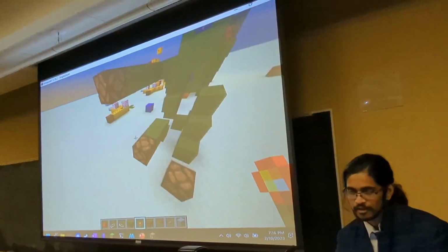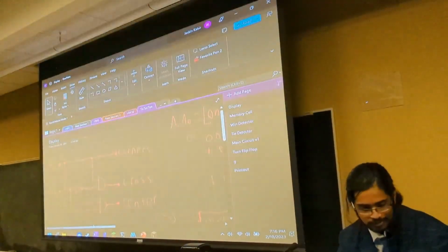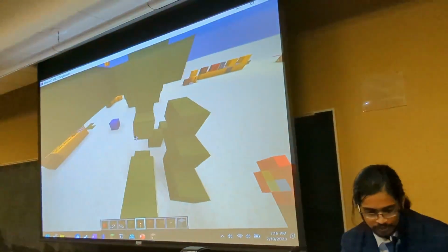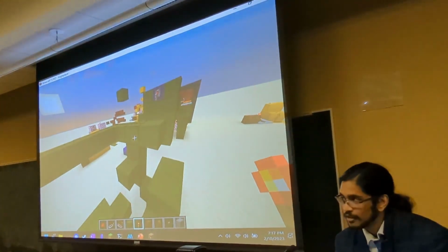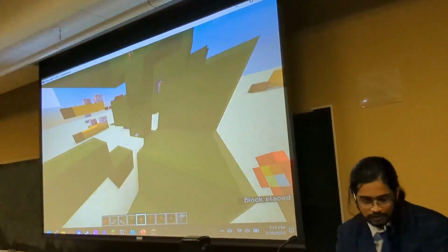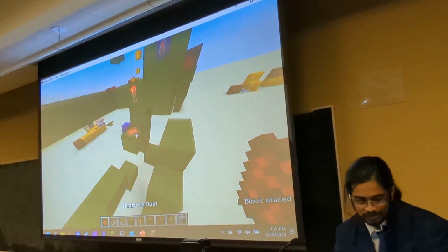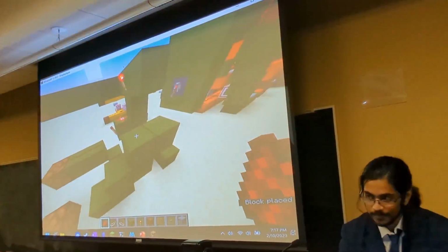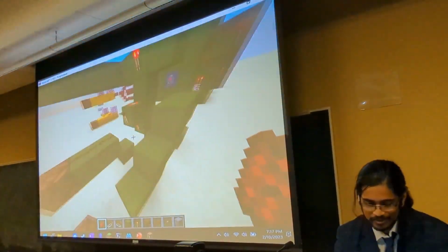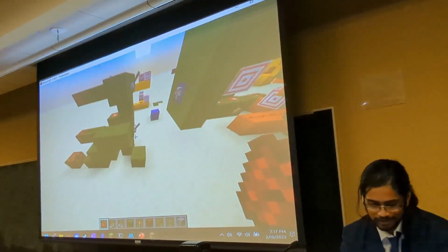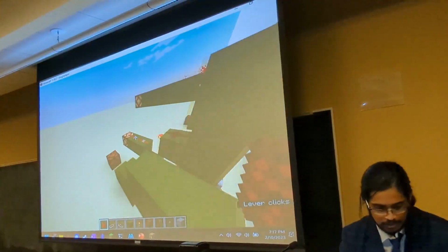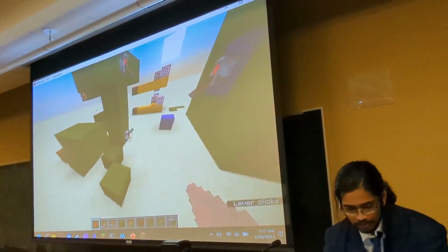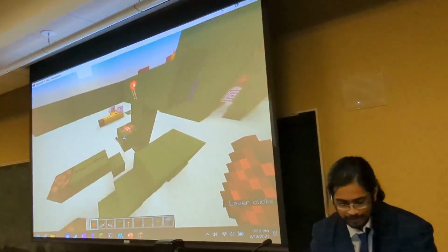So let's say this is the center. Well then, what does that need? That needs an AND gate for A1 and A0, right? So let's do that. A0's got to be a NOT. So A1 not, A0 not, OR them together like that. Put a torch down here, and there you go, right? So two inverted inputs going into an inverted OR output, and so 1, 1 will give us the corners and the center. Now we have to handle this guy being on and this guy being off.